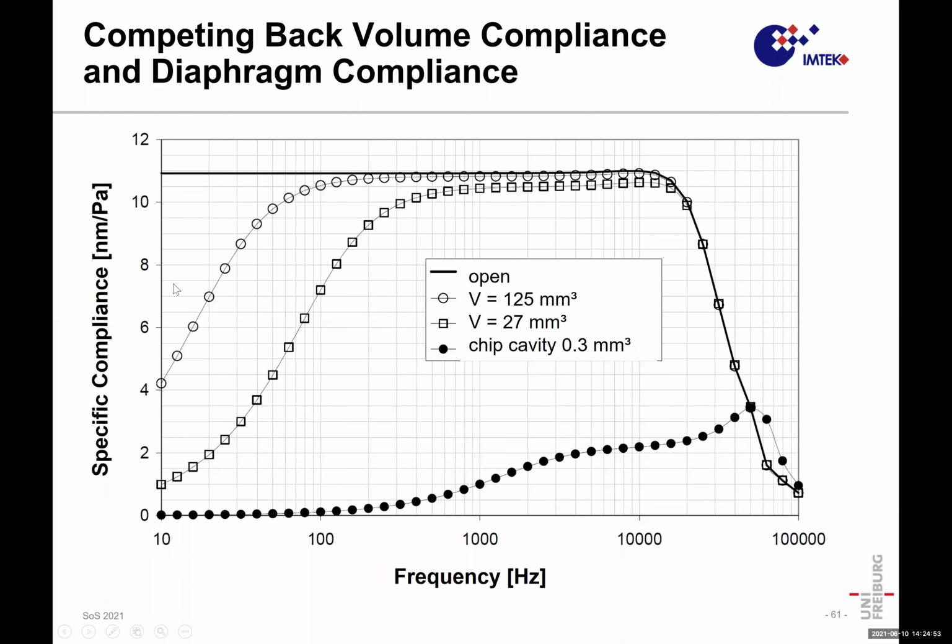But also what we see is that the bandwidth is always reduced on the lower end. So moving from here to there, I know is going with the ventilation. We have kept the ventilation constant, so the hole in the diaphragm is always the same. And of course, if the volume is finally very small, this hole together with the volume can be equalized very fast. And that means we get a corner frequency at higher frequencies. So the bandwidth of this microphone is not acceptable anymore. And we need to adapt then finally the size of this ventilation with respect to the back volume of your microphone.